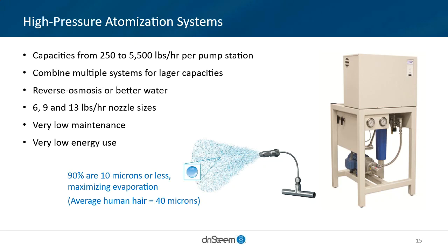One of the items from a marketplace perspective is that a couple manufacturers use this style of pump. It's a water lubricated pump to have lower maintenance. 8,000 run hours is typically what the manufacturer recommends. And in comparison, what else is in the marketplace is oil lubricated, and that trade-off is typically about 500 hours of time in between maintenance intervals for oil.